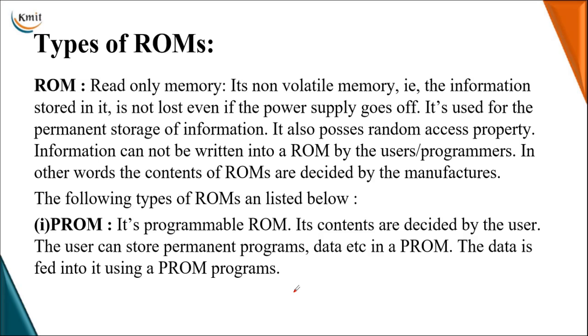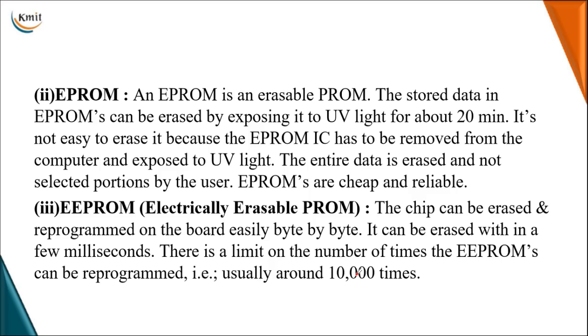PROM is a programmable read-only memory. Only one time you can program that. Upon programming, your data is permanently stored, which is known as PROM. Then EPROM is the erasable programmable read-only memory. In this, you have to expose your chips or the EPROM devices for almost 20 minutes. Then the complete program whatever you have previously loaded will be erased.